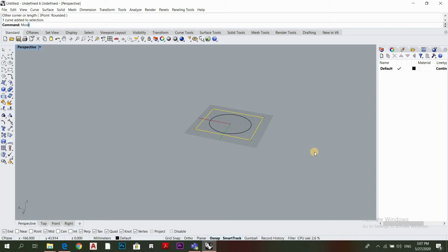If I want to move something, I want to move this, but as we said earlier, everything I want to move would be limited to X and Y because this is 2D. If I want to move something vertically, I have to select that I want to move it vertically here from the command line, or I can just type in V and spacebar. So now it's vertical. I can select it and move it up. So I left this distance, so you can see, guys, the difference between when I'm doing the command. You can see all the different options we can get out of it.